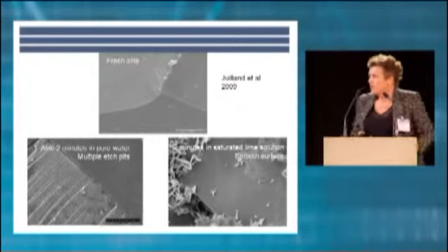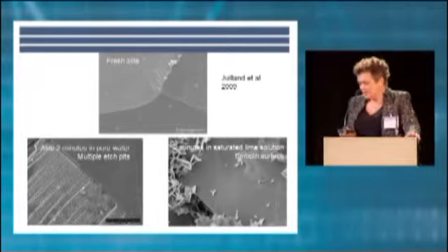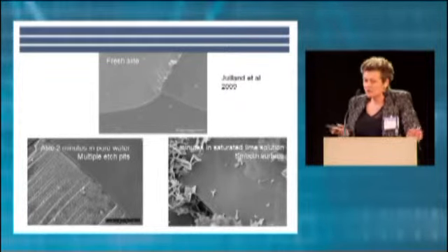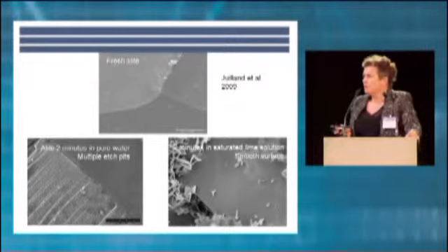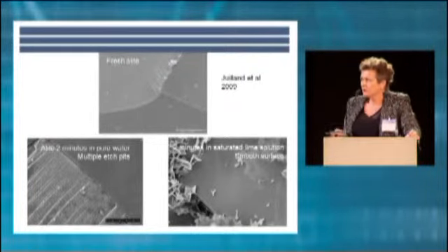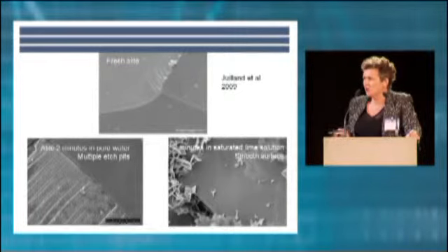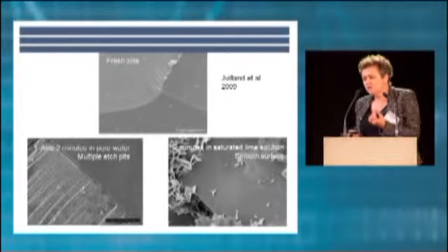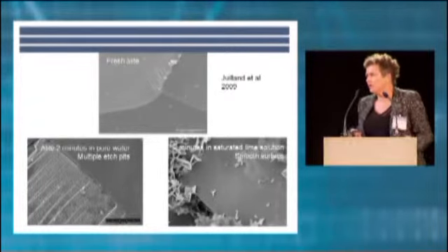So just to take a bit longer to explain, what this slide shows is that if we take freshly manufactured alite, which is the main phase in cement, and we dip it in pure water, we can see very quickly we get the formation of these edge pits all over the surface. So in pure water, the dissolution is very fast, the reaction rate is very fast.